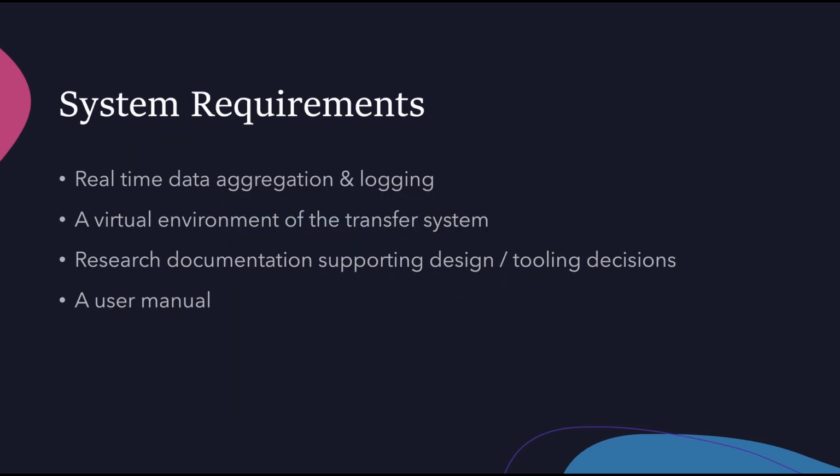Which brings us to the system requirements, which we, together with the product owner, came up with. The first system requirement would be that we have a way to aggregate the data, or the input and output values of the PLC, in real time, and also have a means to log those values. Because if we have access to those values, we can also use them as an input to the virtual environment. And because those values map exactly to the physical machine, if we have them in a virtual environment, we can also create a 2D or 3D representation of the physical system, which would then act and behave in the same way based on what we program with those values.